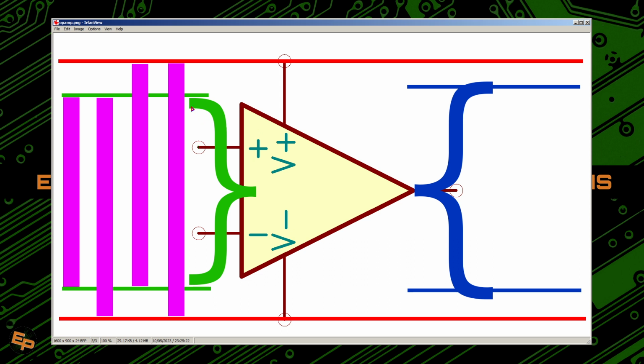And in the fourth case, we have what's called rail-to-rail input-output, which actually are two separate things. Now we're concerned only about the inputs, so we have what's called rail-to-rail, and rail-to-rail essentially means that either the input or the output, or sometimes both, can go up to the positive and negative rails, inclusive. So we no longer have these thresholds in between, right?